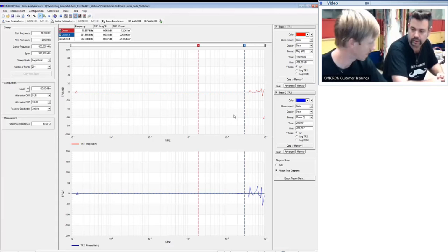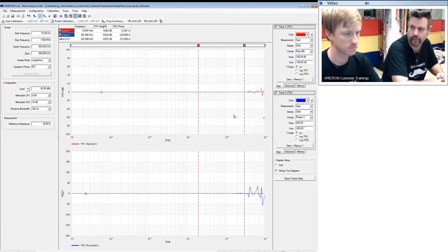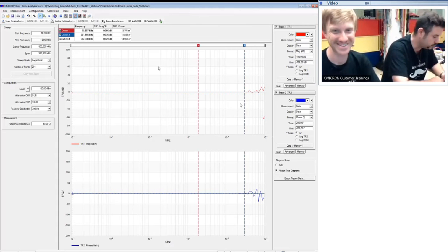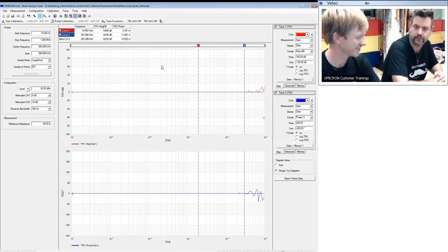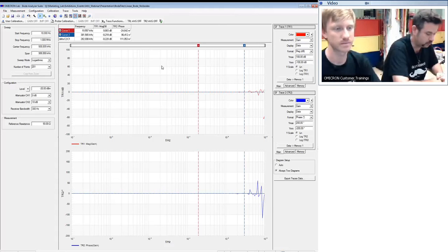And we can't even calibrate that out? No, because calibrating noise won't work, because by calibrating noise, you add noise. Well, and in addition, if the switching frequency would be higher, let's say about 1 megahertz, then we will not see any distortions in that area. Yeah. So for our measurement, it's totally fine. We don't have to do anything. The probes are doing fine.